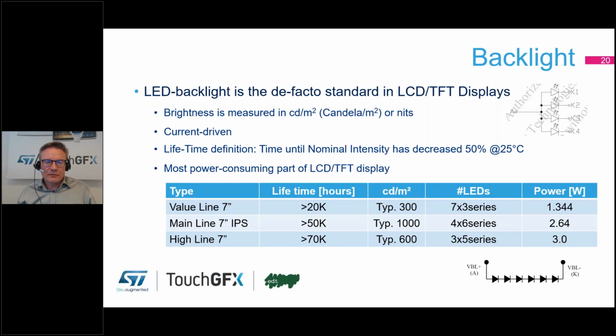And there is another thing to notice here. We will come back to that, but it's quite important and interesting now that you mentioned it, Søren, because for sunlight readability you need high brightness, but that's also where you actually want to fight back the brightness of the sun. So you need the higher brightness, and that reduces the lifetime of your LEDs because you will also have heat dissipating. So that's an issue here.